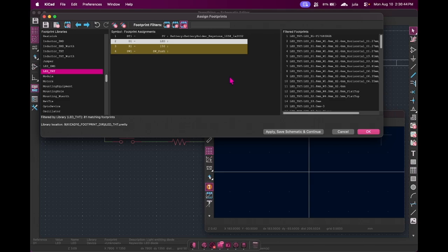You guys aren't going to be manufacturing these, so you don't have to worry about how difficult it's going to be to attach them. You can do whatever, it really doesn't matter, but keep it in mind for when you start to design your own PCB tomorrow, because then you will have to think about the size, whether components will get in the way of each other, and which footprints you're using. We would prefer if you try to save as much room as possible and make your PCB smaller, because bigger PCBs cost more.